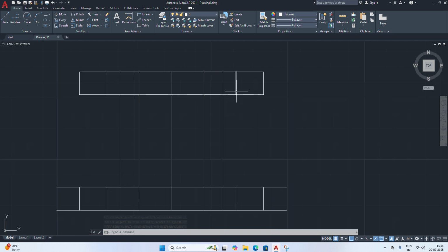Now here there is a thread hole, and there we want an M12 thread. So this line we will offset through 6 mm on either side. Now this line we will offset through 1 mm, offset through 1 mm, inwards, towards the center. Okay, now you got this much.